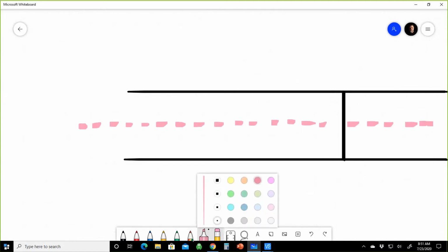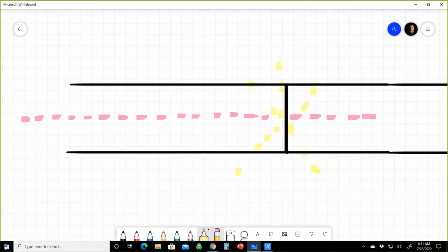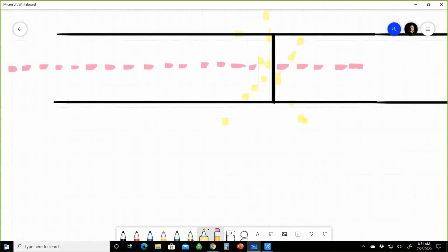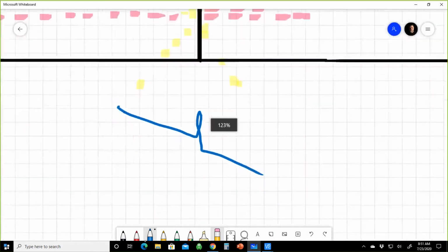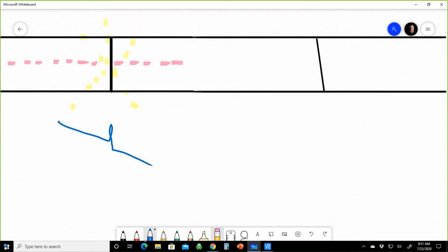Anytime there's some sort of discontinuity or change in material type, it's going to change the way that the backscatter comes back. Then we'll detect that on the OTDR, and it will display that in a certain manner. If it's a connector, it's going to display it as a spike because there's reflection, right? When you look at this, it means reflection to me. If it's just a splice, then you're going to see just a drop without reflection. And so this is important to understand.